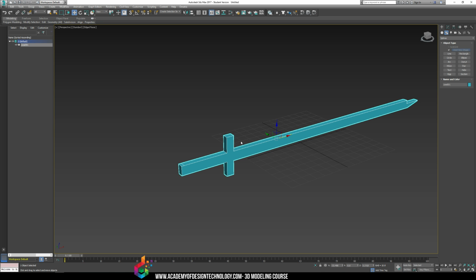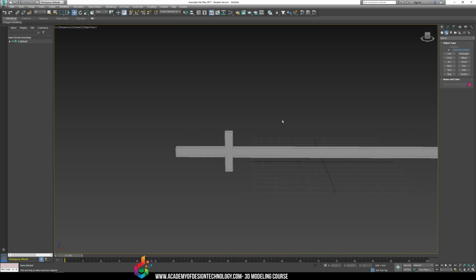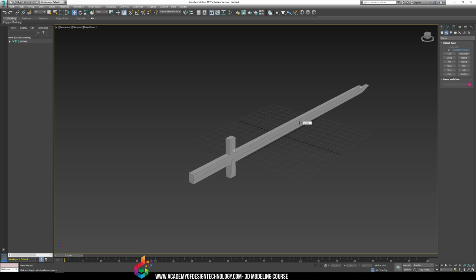To do that, you use a shortcut key, Alt-X on your keyboard. So I hold this model and I push Alt-X, and that makes it see-through. That means I can start developing the other sword, the final model, right beside it or even inside it. Place it inside, and now I get the exact size and dimensions of the model that's being used in the game. The size was correct. Our director said that size works really well, model that, then we have that there perfectly.